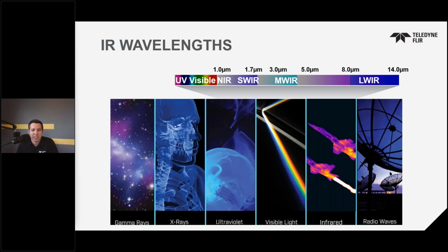Finally, we have longwave. There are a few different detector technologies that address the longwave. It's also an interesting waveband because there are a lot of photons out there. This enables better measurements at colder temperature, the use of cheaper detectors, and it allows for cryo-cooled options that achieve very short integration times in comparison to their midwave counterparts. Another interesting feature of the longwave is that you experience fewer solar artifacts and solar glare. At the end of the day, all IR wavebands are going to be complementary to one another for the unique capabilities or properties found in each range of the spectrum.